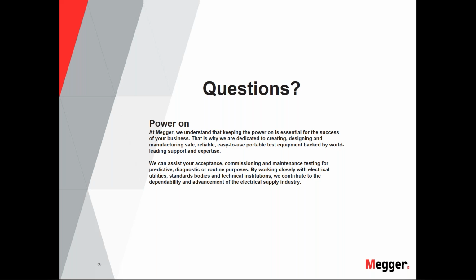Thanks. Next, we have a comment that I think you might want to follow up on. The comment is: I've seen reverse power used on a controlled shutdown to protect the unit from overspeed, to validate that the stop valves have actually closed and removed the power from the prime mover before opening the generator breaker. Yeah, I'd like to comment on this one.